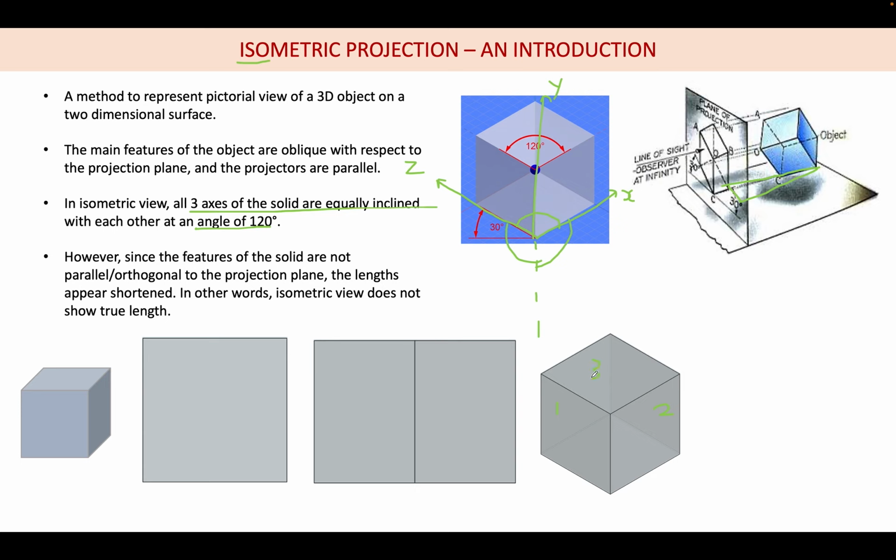So the tilting I am doing is, here some tilting and here some tilting. After the tilting, if you observe, all the axes are equally inclined to each other, that is called isometric. So simple. I have a cube, first look at it like this, then tilt it horizontally, then tilt it vertically, and ensure in such a way that all the angles will be equal. If you closely observe this vertex and the exact body diagonal opposite vertex, they will be coinciding with each other.